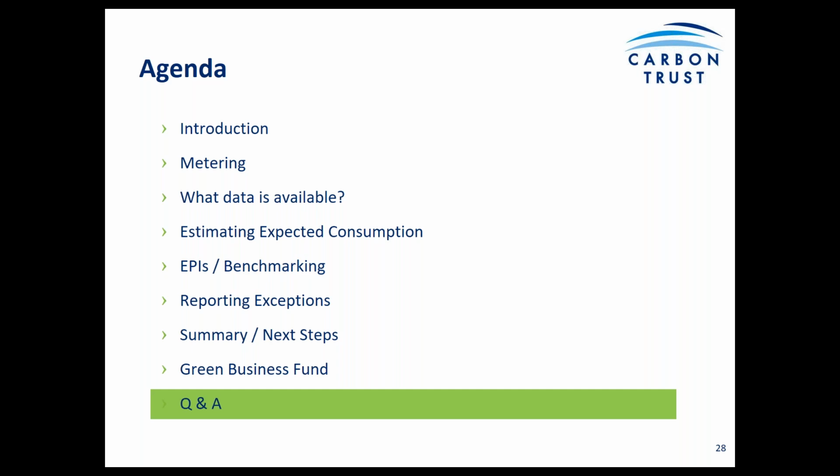If you did want to, rather than setting energy performance indicators for the office and warehouse separately, if you have a smaller site, that might not make sense. You might just want to have an EPI for the whole site. Then what you could potentially do would just be to combine these figures, just making sure that you're obviously weighting them by the floor area covered by each one.